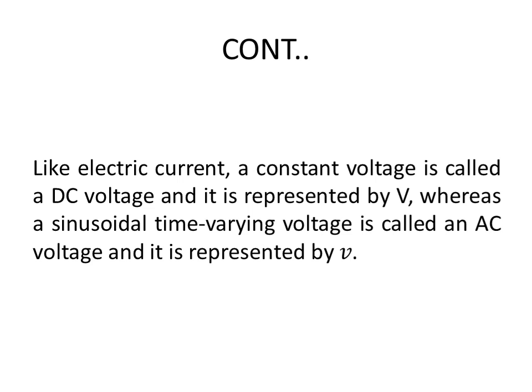Similarly, like electric current, we also have two types of voltages. One is DC voltage, next one is AC voltage. Of course, the definition is the same, but in place of current, we simply represent it as a voltage. If the voltage magnitude is constant with time, then it is called DC. If the voltage magnitude and direction are varying, if it is sinusoidally varying, then it is called AC voltage. That is simply represented by small v, just to show the difference between DC voltage and AC voltage.